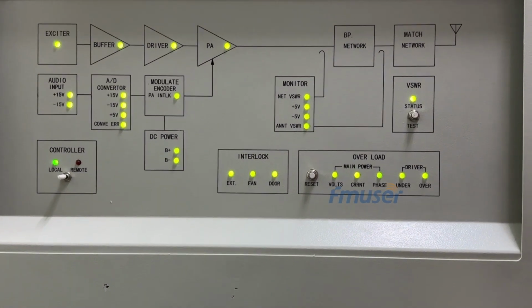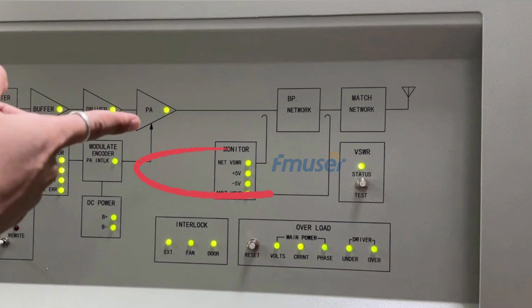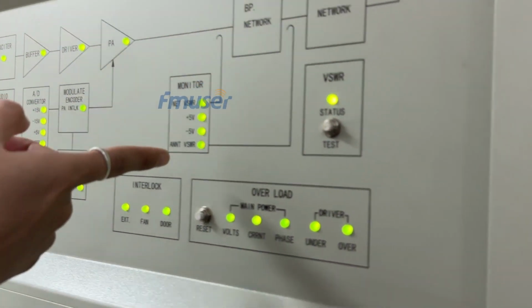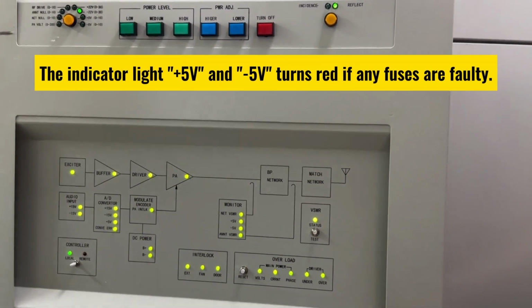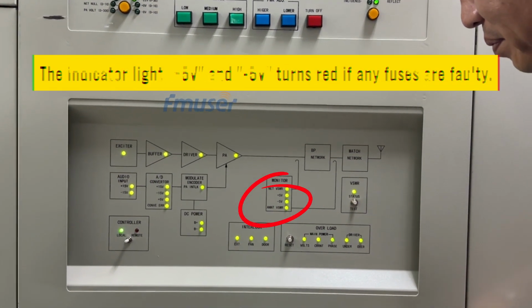On the monitoring panel, there are 2 indicator lights labeled positive 5 volts and negative 5 volts. The sampling board itself is equipped with 2 fuses. If either of these fuses is missing or damaged, the corresponding indicator light will turn red. These lights serve to monitor the voltage of the sampling board and ensure it is within the normal range.